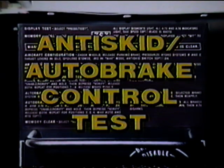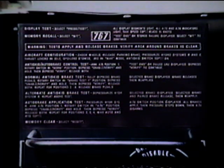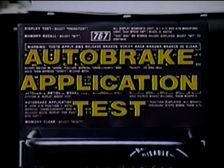The anti-skid Autobrake control test provides a complete electrical check of the anti-skid and Autobrake systems. The normal and alternate anti-skid brake tests provide an operational check of the normal and alternate anti-skid valve functions. This test causes the valves to release brake pressure and reapply. The Autobrake application test provides an operational check of the Autobrake module function. This test causes the module to apply brake pressure to the level selected, releases the brake pressure, and disarms the Autobrakes.